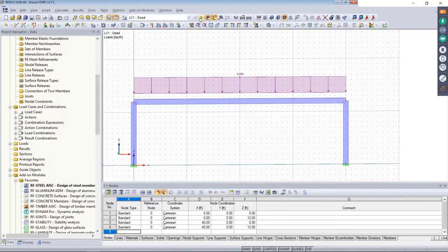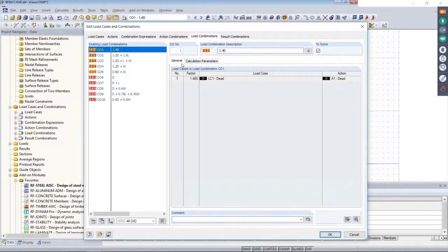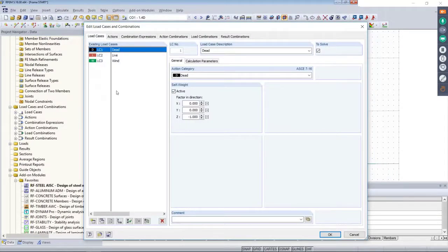The load follows. We're looking at the same thing for live load, wind load, just like what we saw with our first example. Now, a couple of changes though. So we obviously need to add in a torsion load if we want to check warping torsion and such. So let's really exaggerate that here. I'm going to go back to my load cases, and we jump to the load cases tab. I create a new one, and we'll call this one torsion.